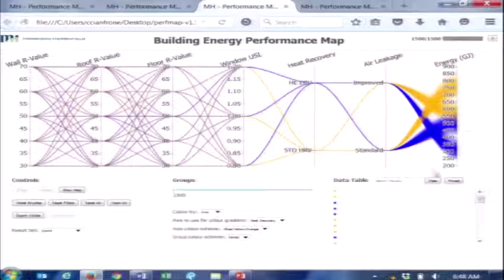And so in terms of energy results, you could do everything else in terms of optimizing R values, use the best windows, roofs, walls, floors, and you're still just barely going to get to any of the design solutions that have the improved heat recovery. So it becomes very, very obvious just by looking at this trend that if you don't do that, that's the lowest hanging fruit.